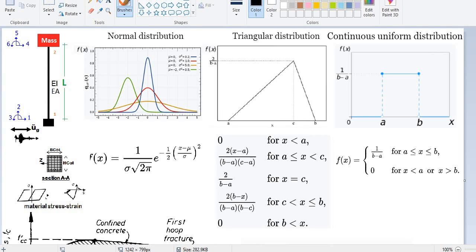Hello guys. My name is Salar Delavar Qashqai, and in this video we're going to talk about sensitivity analysis in structural engineering with this example. We have one column with 6 degrees of freedom and mass at the top and seismic acceleration at the bottom of this column, and with different sectional properties and material properties, we want to do the nonlinear dynamic analysis and find some parameters.